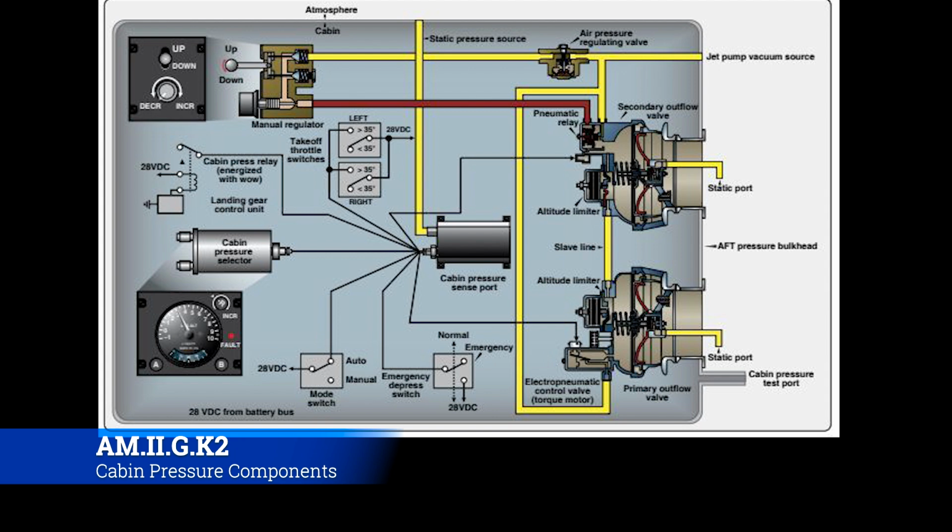Now, if we need the water to come up, then we might close the plug a little bit, maybe cover up only half of the hole, because then we'll get a certain rate of water climbing in the bathtub, or maybe we adjust the water that's coming into the bathtub. If you think about it like that, this is pretty simple. The air pressure is going to come into the aircraft through bleed air or compressed air, or whatever the means is for this aircraft, and then it's going to exit at the outflow valve. And so those two outflow valves right there are pretty key to maintaining that pressure.